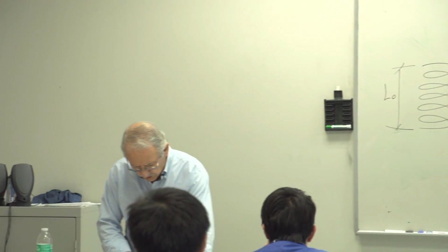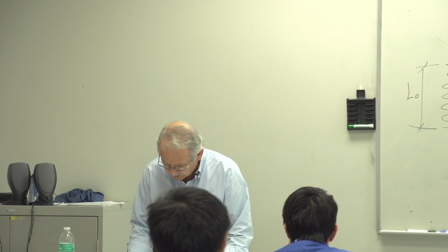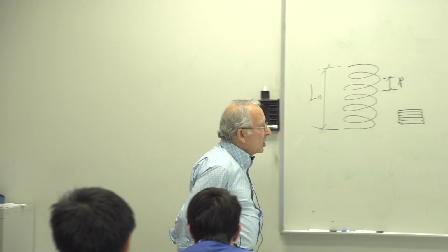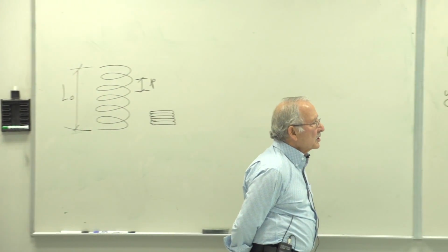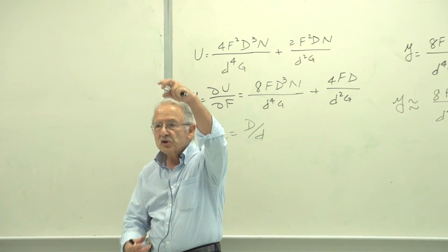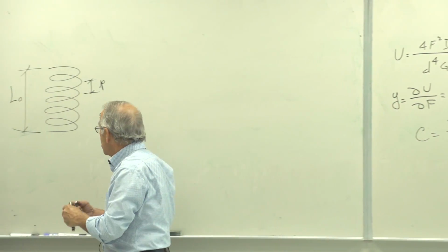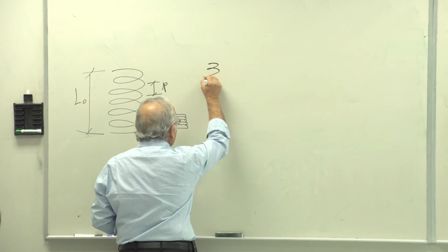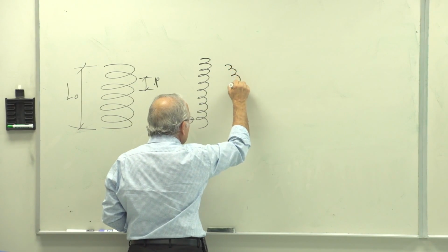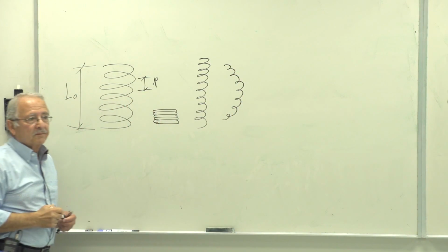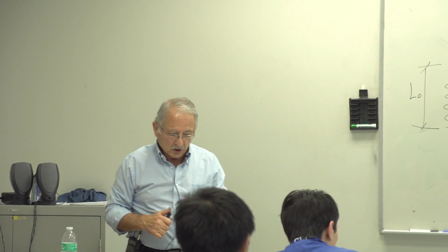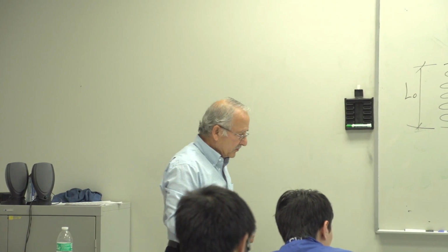Now, let me just take a quick look at your book, Deflection. Okay. Very similar to columns, springs may also buckle. If you have a very long spring, long and narrow like that, and you try to deflect it too much, there's this possibility of buckling. Just like regular buckling that you studied in strength of materials.